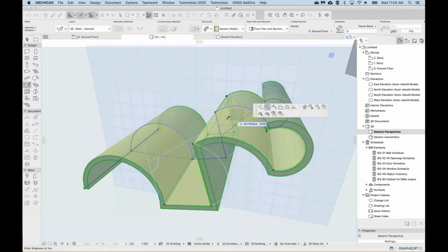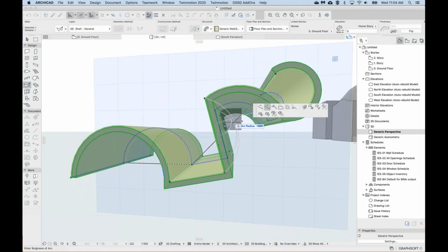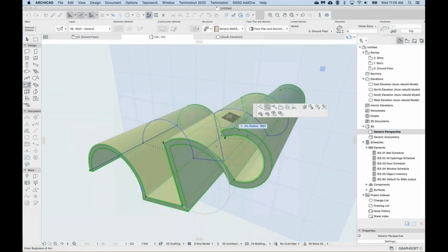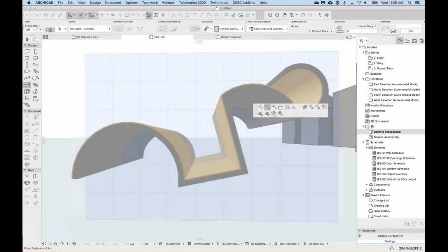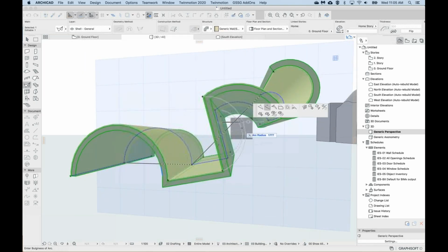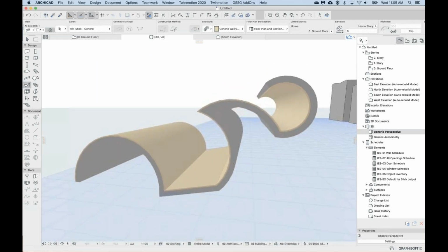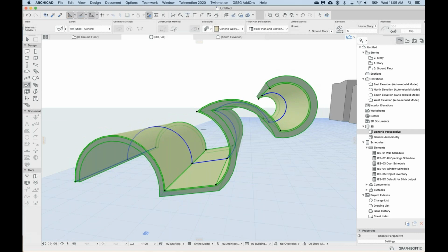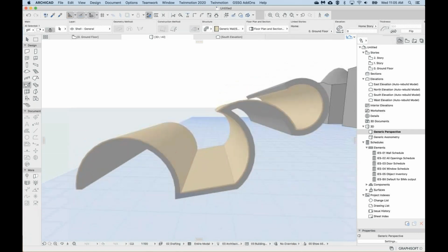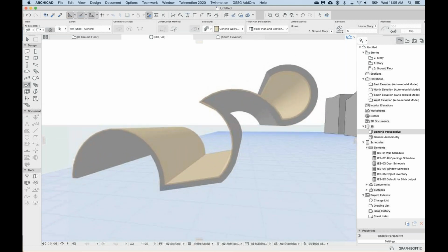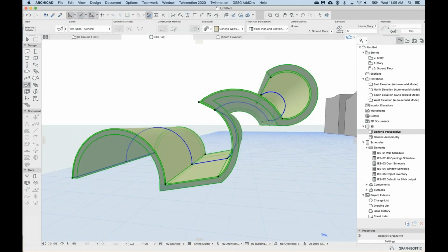Because there's a body here and it's trying to snap to that body, you may need to move the cursor around a little bit to be able to curve it easier. Because otherwise, if you're trying to curve, then it's trying to snap to other surfaces. Trying to just move the camera around, and then I can curve. So usually you just need to modify the camera position a little bit, just so you don't have other geometry in the way.